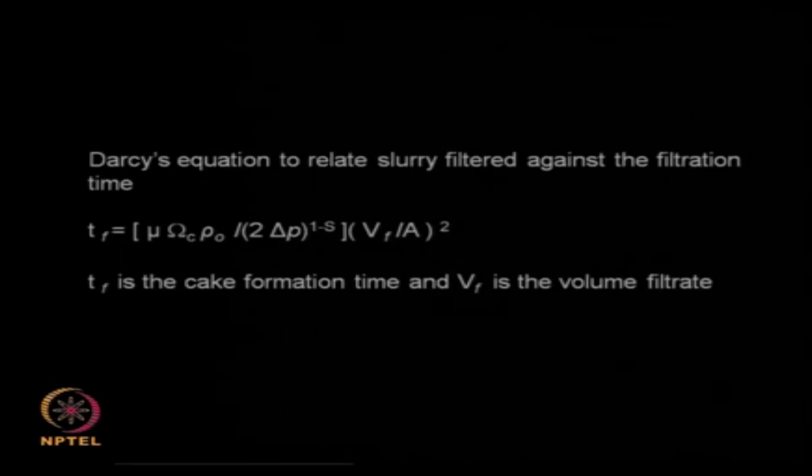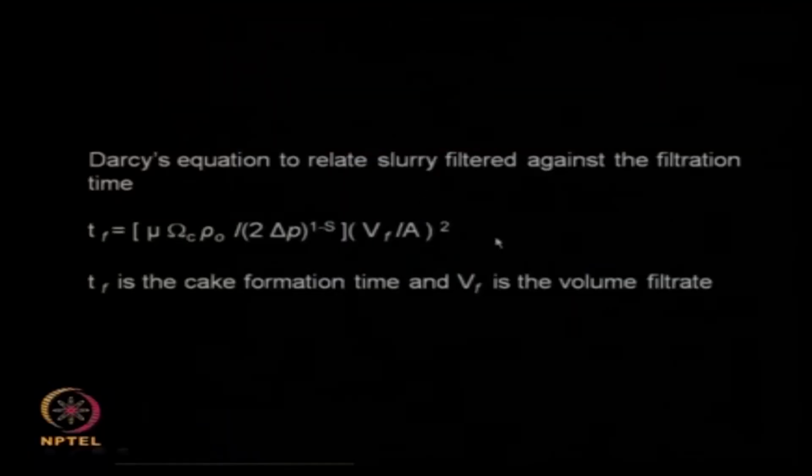Remember that there is cake formed only when the drum is dipped inside the slurry tank, whereas when the drum is outside the slurry tank there is no new cake being formed; the cake is getting washed, dried, and cut. So during the first stage, when the drum is inside the slurry tank, we can still use the Darcy's law relationship as we derived previously,